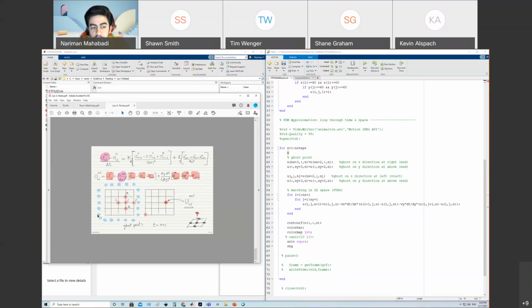Minus 1, which, as I explained last lecture, in MATLAB we cannot have anything less than 1, right? So everything should be integer numbers starting from 1. So we're going to shift this to 1. This will be 1, right? Okay. So this is index 1. And if this is index 1, the very last one is nx plus 3, right?